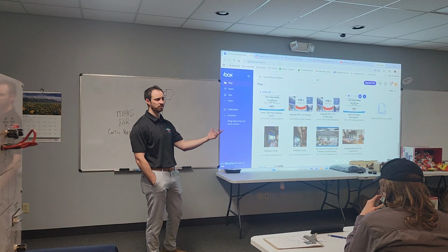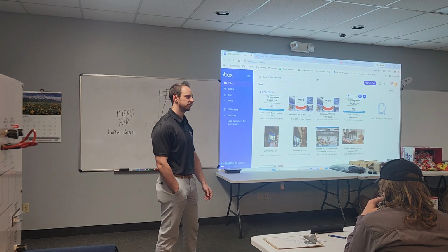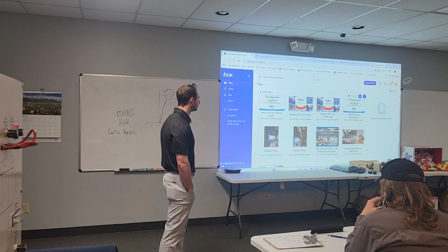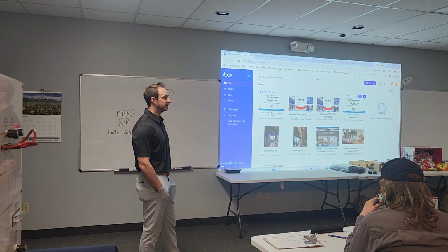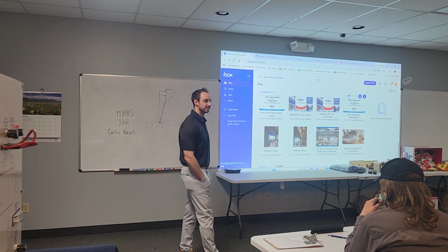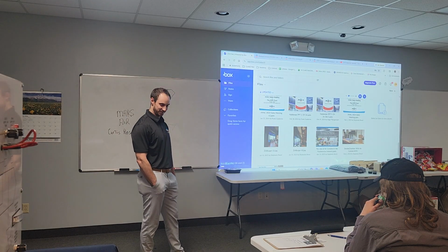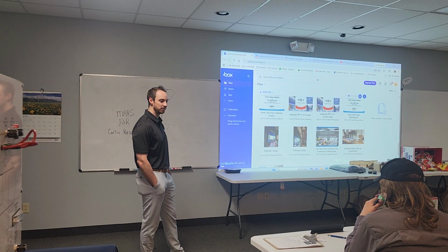We wire that all from the factory, but it would be more from the troubleshooting side if you wanted to test continuity and things like that. Can't have the heat if the fan's off, you'll burn it up. You don't want that to happen. Correct. If that happens, shut that off immediately. Those coils can heat up pretty quick.